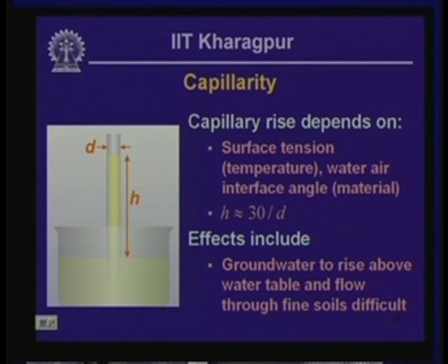Capillary rise depends on the surface tension, and because the surface tension of water depends on temperature, the amount of capillary rise will also depend on temperature. It also depends on the water-air interface angle, which is a material specific value.